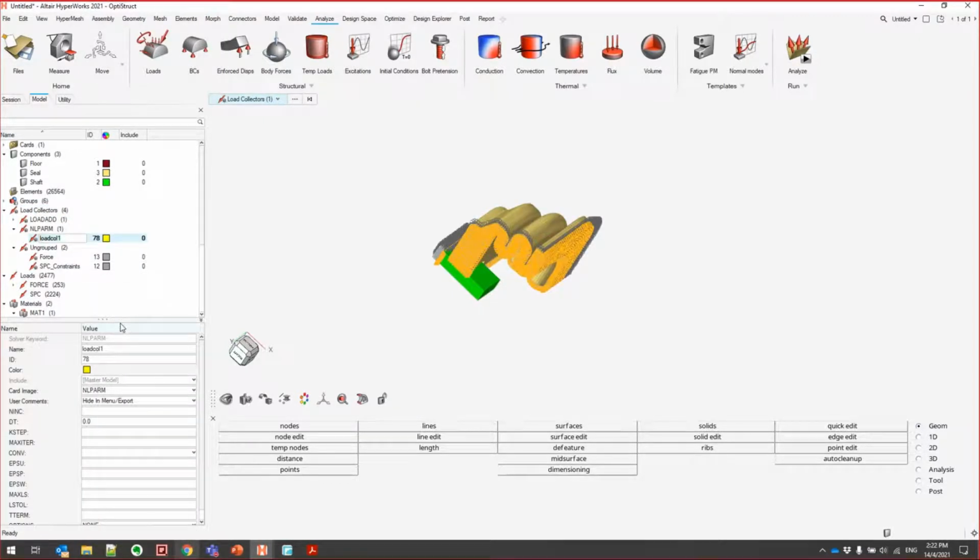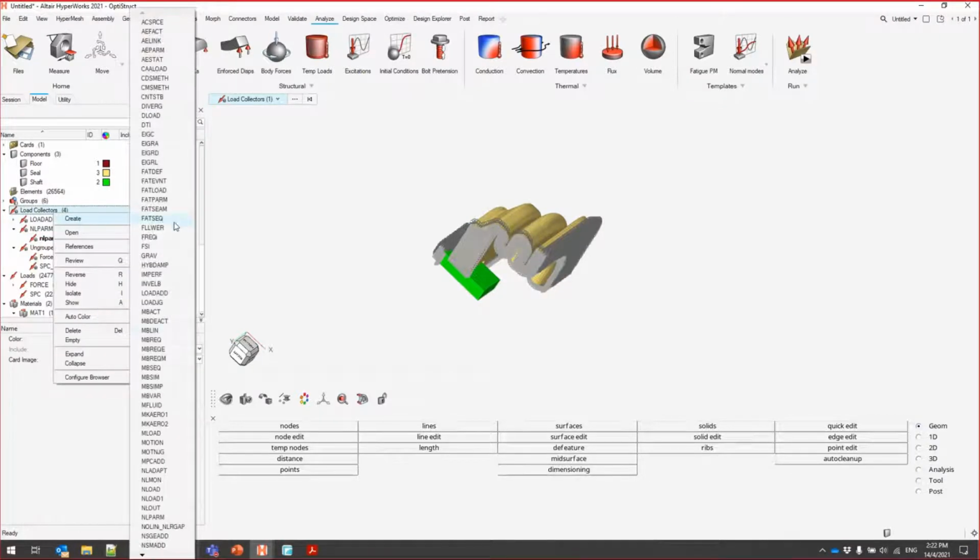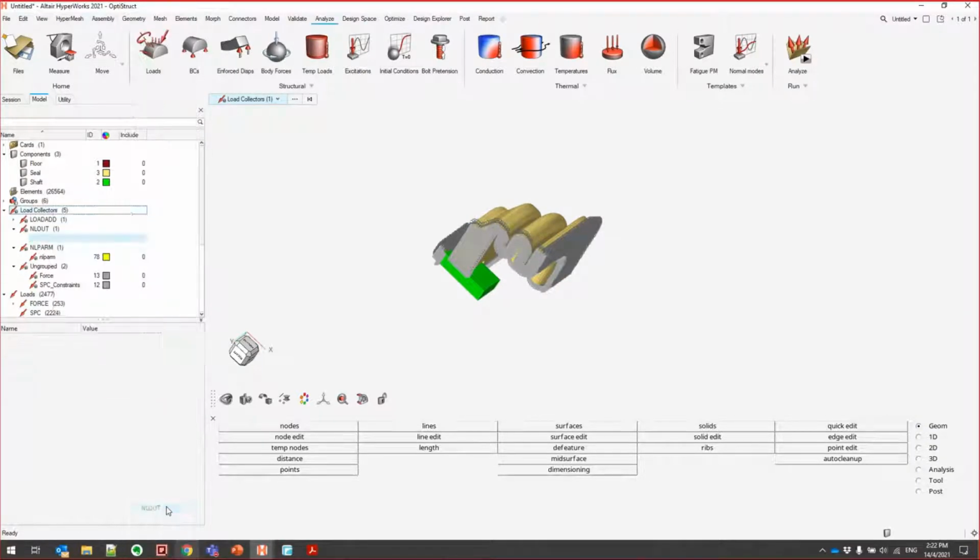We need the NLPARM. Okay, that is always needed. What is the initial time step? Then we also need the NLOUT. Not need, but it's good to have it because it will organize the way we output later on, right? So how many outputs do we need? For